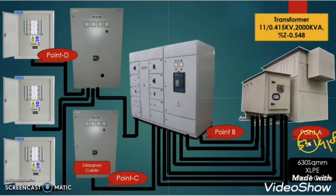So we can write here that the maximum prospective short circuit current at the transformer level is 53.14 kilo ampere. It means if we are designing any breaker at the secondary side of the transformer, then we have to choose a breaker which has a short circuit current capacity of more than 53.14 kilo ampere. So for that we will choose a breaker which has a short circuit current capacity of 65 kilo ampere, as it is greater than the calculated prospective short circuit current.